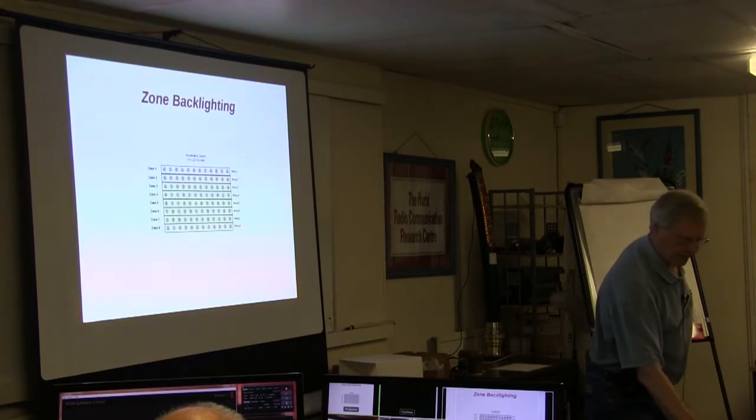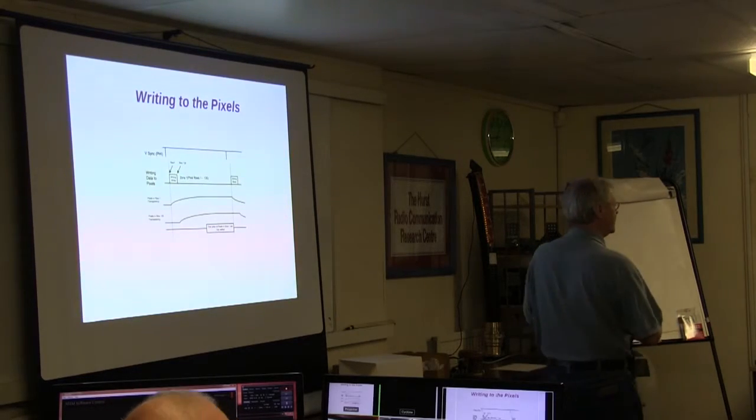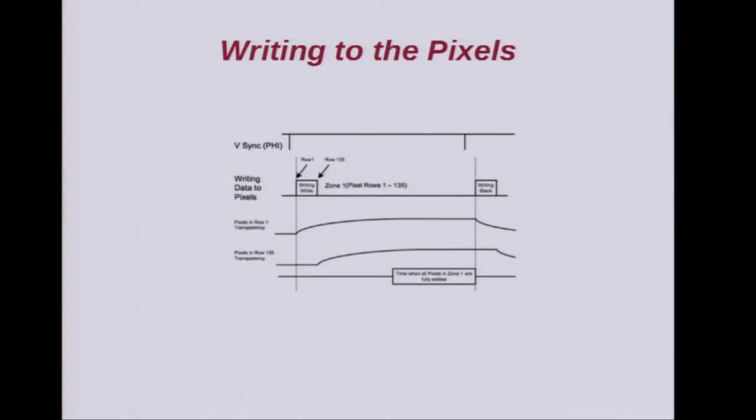But another thing occurred about this time. LCDs were getting quite good at picture displays now, and the contrast ratio was kind of adequate and the gamma was pretty good now. But one of the problems was the blurring. If you remember, the original LCDs were really bad. You had to have what was called mouse trails, because every time you moved the mouse you couldn't see where the cursor had gone. So much later on it was pretty good, you could see the cursor, but people started to notice that fast moving images, sports and so on, were blurring the image.